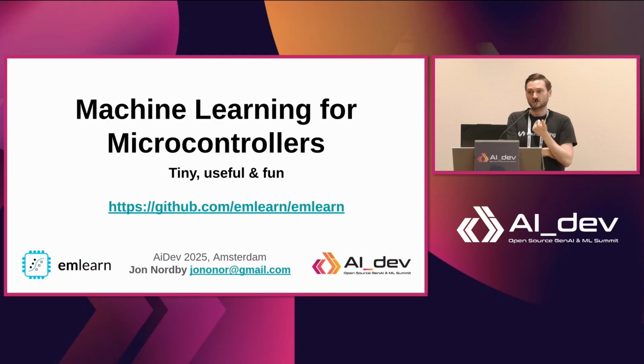Yes, it is quite relevant. ARM Cortex-M4 is a quite established, almost 10-year-old microcontroller now, very typical to use. That has the DSP instruction set for SIMD. So usually you can do 8-bit, 4 at a time, and that's quite useful.